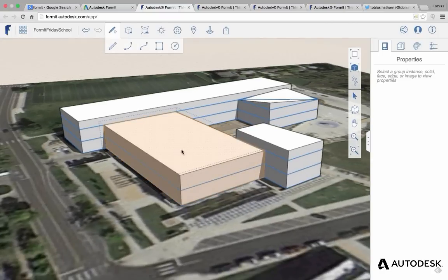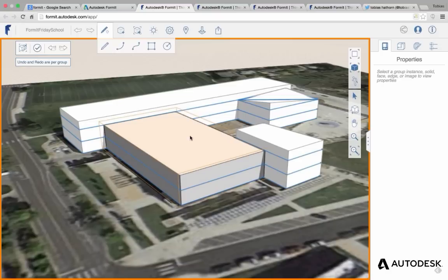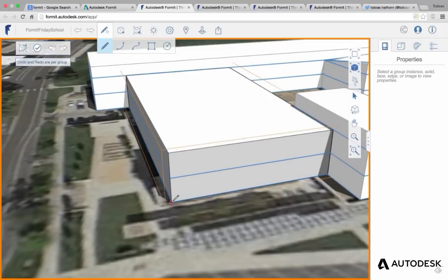One is to double click to edit this group and then select that edge so I know how big that is. The other way is to use the line tool as a measuring tool until we implement a real measuring tool where you can click one corner and then come up and, using the inference engine, find out that that piece is 30 feet.